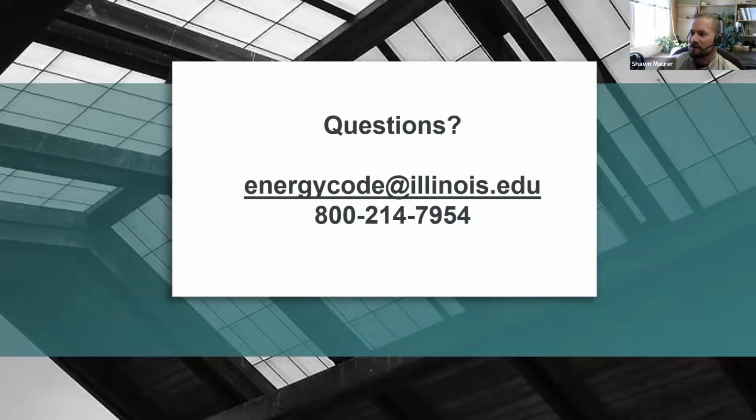So touching on the R value question for tapered roof insulation, just to confirm, it is possible that there will be a decrease in the overall R value requirement in portions of the roof. But given parapet heights and typical manufacturer requirements for insulation installation, flashing, and things like that, the general construction practices should keep a relatively consistent R value across the roof and not have huge amounts of tapered insulation.